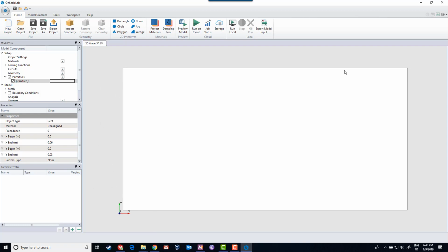So my model is a steel plate, I'll make a hole in the middle, and I want to assign a pressure here that will vibrate along a certain time function, called forcing function here. So I'll assign this load to a time function with a certain time distribution, and I'll observe how the wave is actually propagating into the steel material.